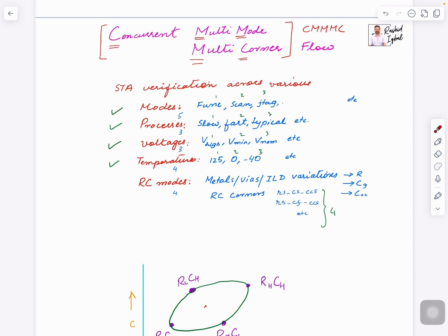The way you disable it, this is more of a timing disabling: setting case analysis, setting false path, defining a clock, not defining a clock, stuff like that. Making clocks asynchronous. So you can play with those things by putting your entire logic in one particular mode and another one. But typically we have one functional.